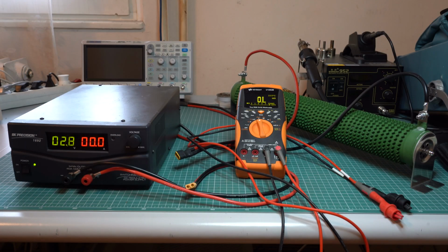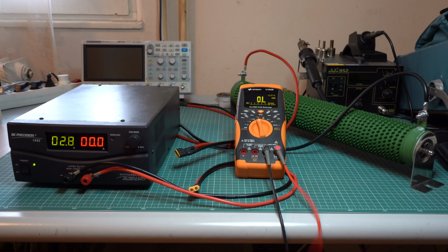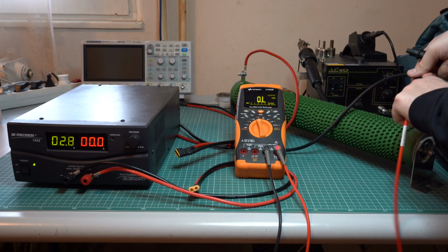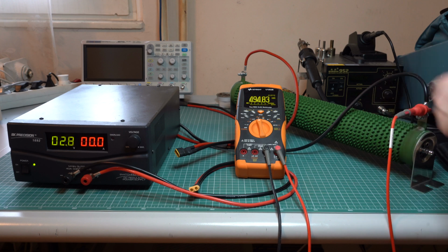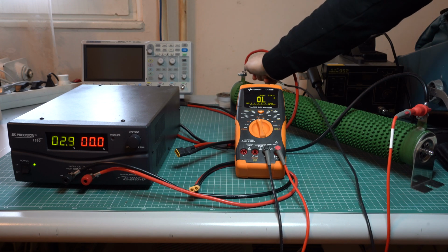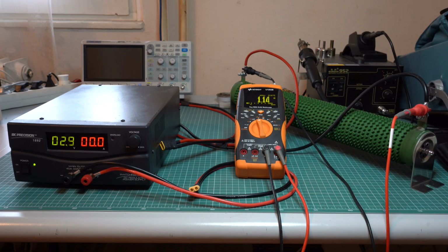First of all, let's start by measuring the resistor to make sure it's a 1 ohm resistor. To do this, since we are working with a really low value, I would like to compensate the resistance of the test wires. So to do this, I will connect both of them to one terminal of the resistor and just cancel out this value. And now I can move this probe to the other terminal of the resistor, obviously with the resistor disconnected from the power supply, and now we get a value which is close to 1 ohm.